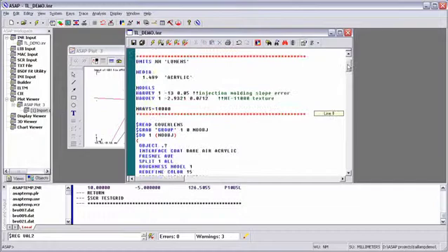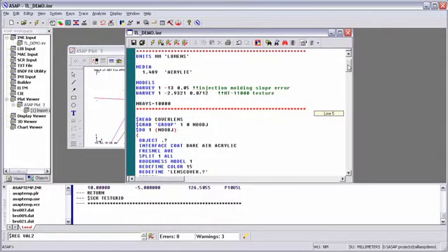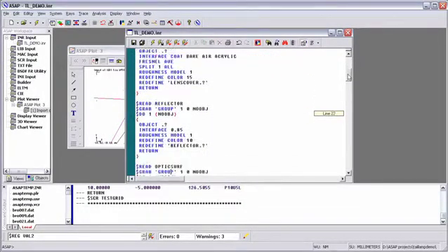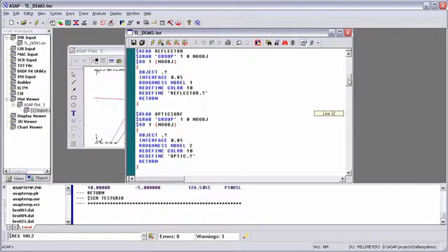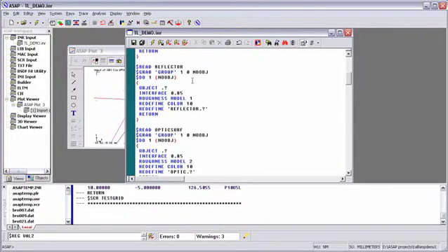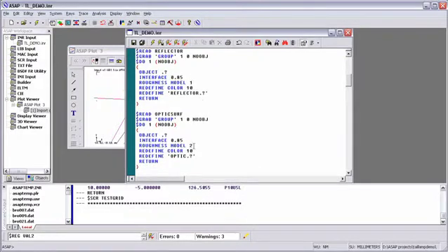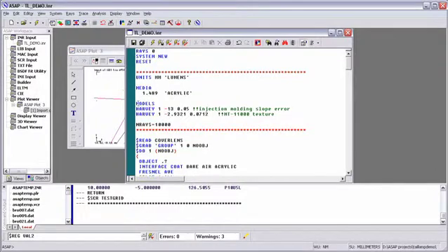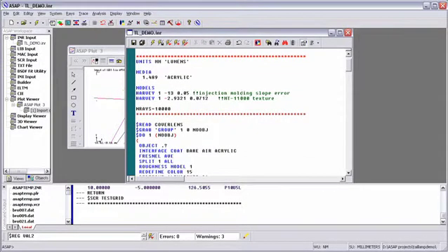I mentioned up front that I didn't do the material assignment to the geometry with the IGES translator to allow me to change the parameters of the design quicker. One of the things I've set up in this particular file is roughness models that simulate different surface finishes, one of them being a simple model for simulating injection molded parts, because they're not going to be perfect, so it simulates a modest amount of slope error.